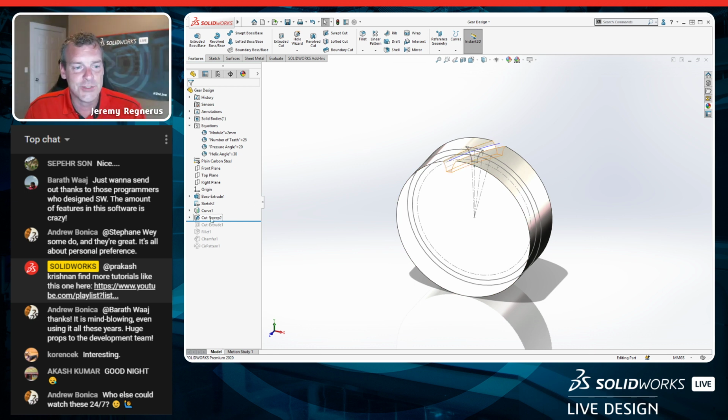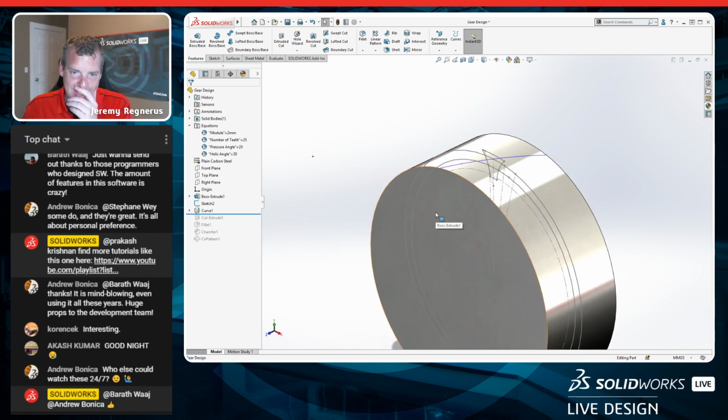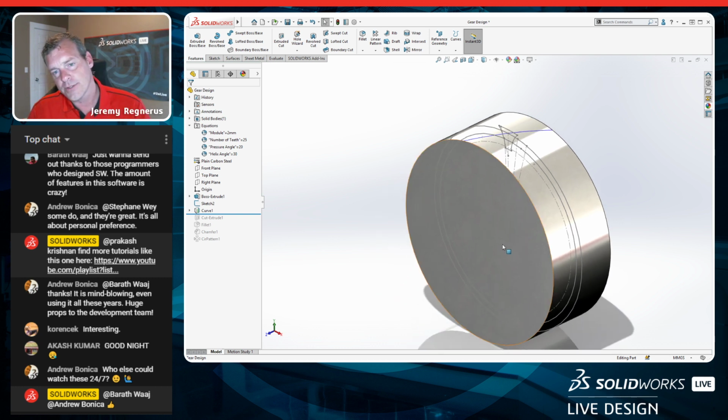All right, so not a swept cut. So how are we going to create a loft? Do I have to draw this sketch 2 more times? I saw this in one of the earlier live designs, and this is an old, what we call an oldie but a goodie, derived sketches. They're really powerful and they're really useful in cases like this.